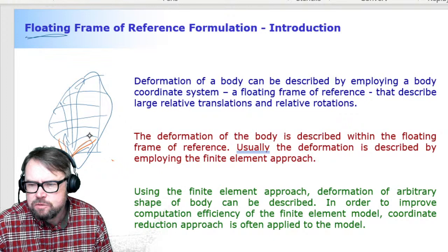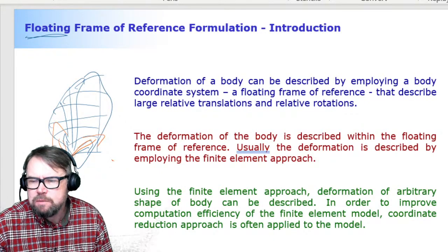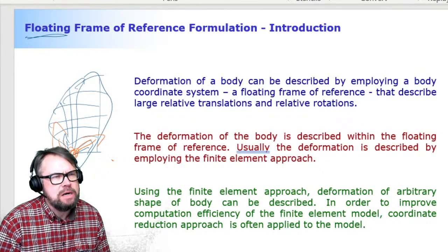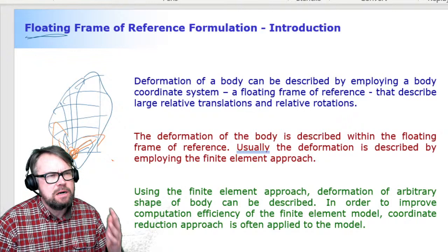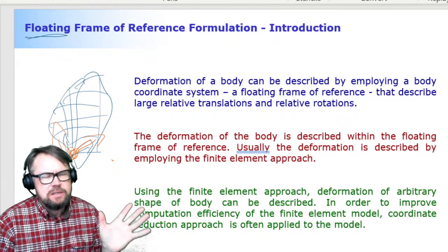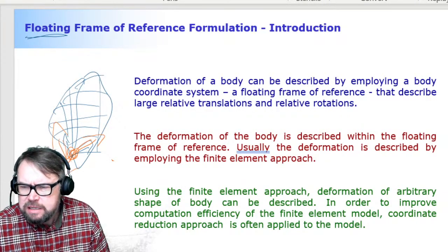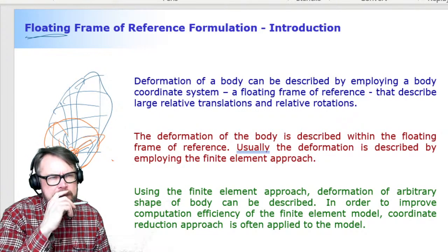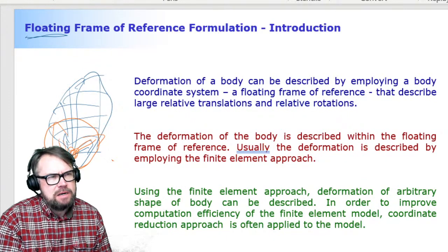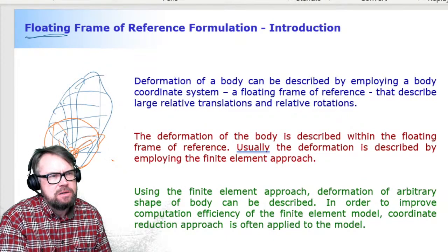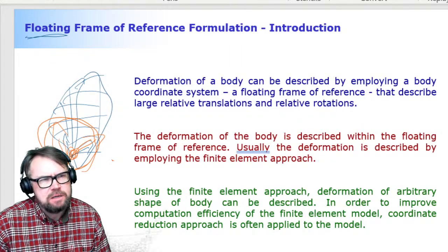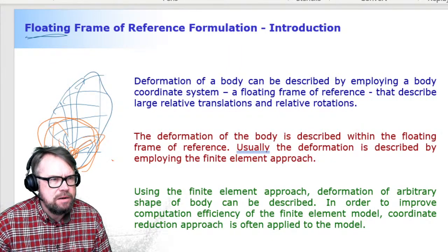This is a reference coordinate system. So the deformation will be described with respect to this reference coordinate system. And the reference coordinate system will be the one accounting for the large translations and large rotations. So in summary, this coordinate system's behavior is described by using multibody system dynamics. Deformation with respect to this coordinate system is described by using finite element modeling.